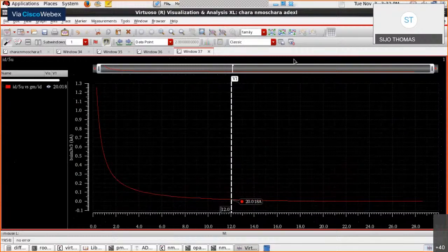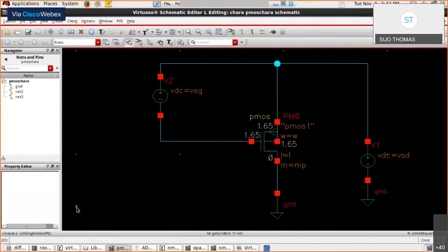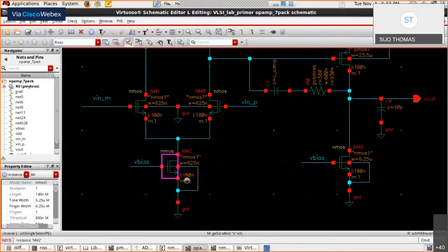Now we can look at the PMOS curves. From this curve itself, one minute, Naveen. We have a tail transistor that is again NMOS. There also the gm/ID value remains the same as 12, but the ID value changes, which is double the ID value you got for the input MOSFET.